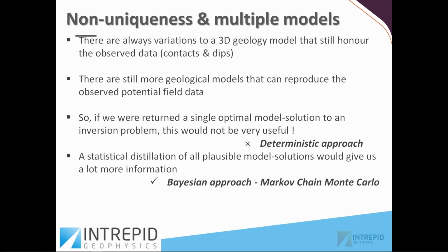Inversion without constrained information will be treated like a blind inversion. The inversion may give you any kind of geological model, which doesn't have any geological sense and probably doesn't have any correlation with your geological model. But if you provide some additional information, such as drilling or any surface constraint or any subsurface information that you may rely on, then the inversion may predict a few solutions that are the most probable ones.